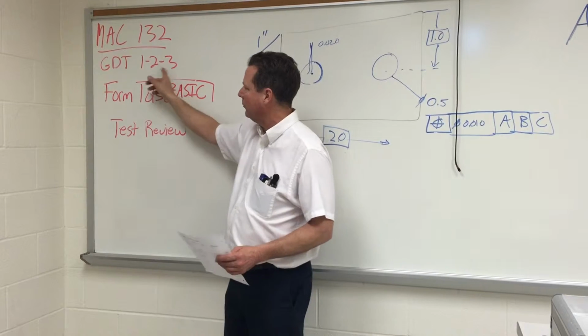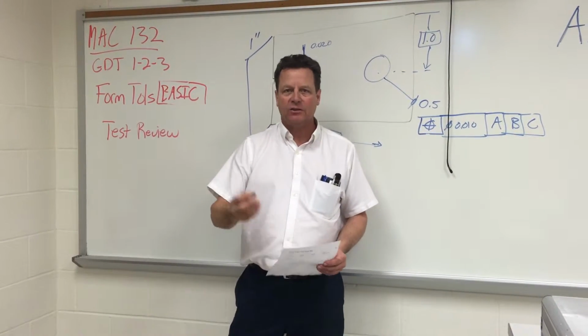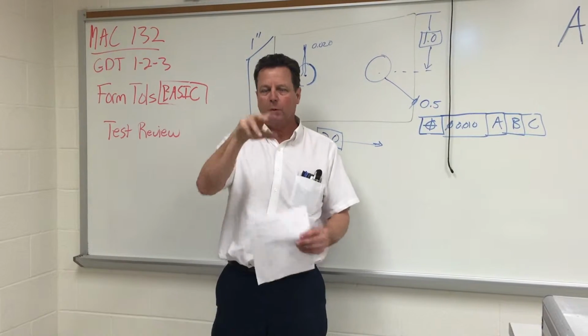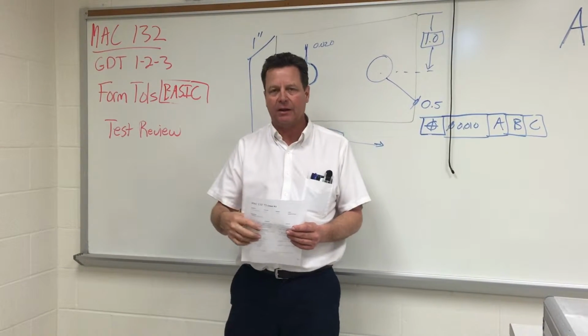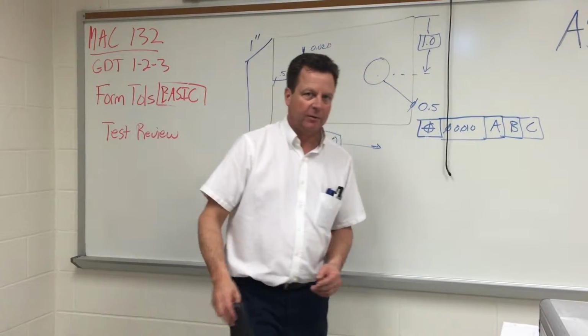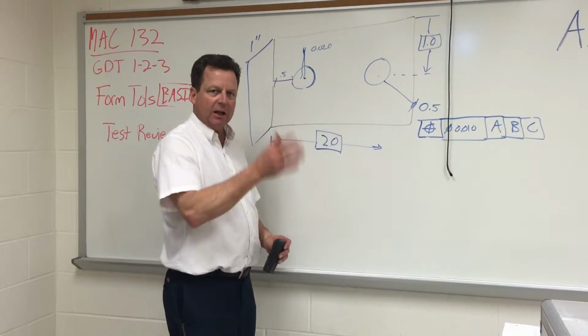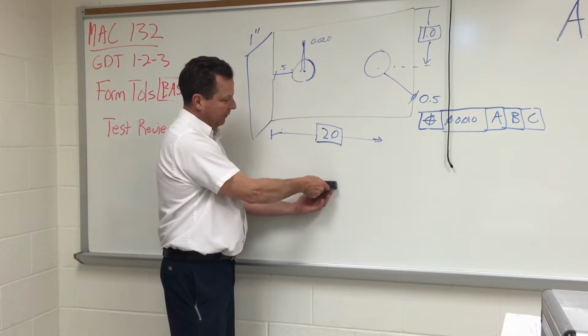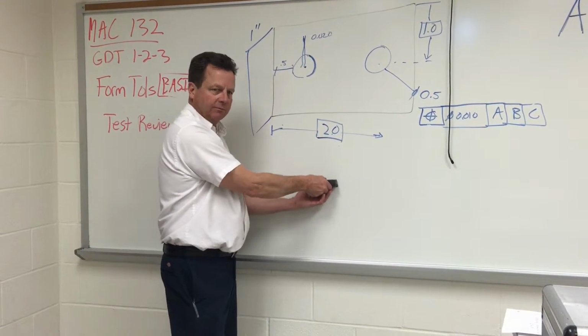The 3, 2, 1 rule of GD&T is that you must have 3 points of contact on the primary datum, 2 points of contact on the secondary datum, and 1 point of contact on the tertiary datum. So that if we have set up our milling machine properly, then we will have a flat surface to set our part down.